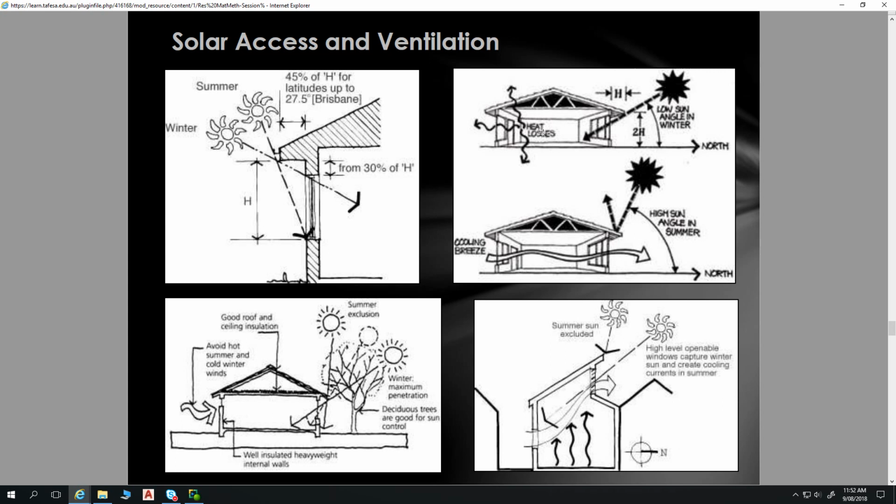In this regard, buildings which are hundreds, if not thousands of years old, that have these big mud brick cooling towers that draw in wind from the windward side, drive it under the house, comes up through grates, and then sucks out the hot air from the top of the house on the leeward side. So very slight breeze, air conditions the house with no input of energy at all. Some amazing design stuff that possibly we could use in our very dry, hot climate in South Australia.